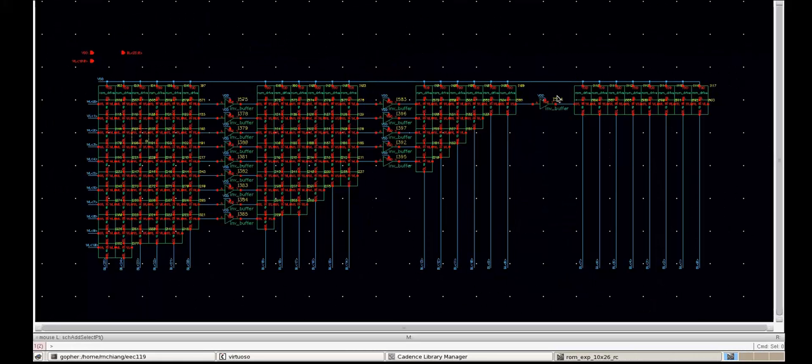So in the ROM here, it's a 10 by 26 bit ROM, and all the bit lines here are just always pulled high until you select a level that pulls a certain bit line low. So excluding this first line here, which is just a 0, you can see that these values here are exponentially increasing. So the first row here, the lowest brightness level, has a pulse width of 10 ones, and the highest has a pulse width of 24 ones, and then the rest here are just zeros.